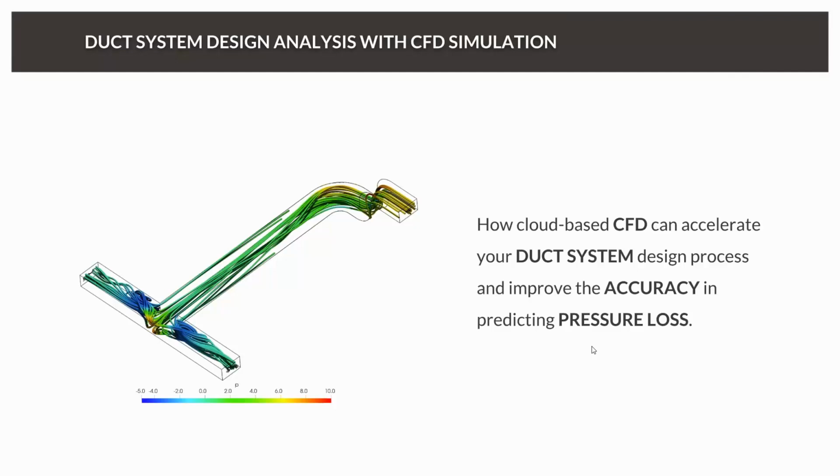And in the past, or let's say the old way of determining these coefficients, is really to put the segment on a physical test rig and measure the pressure drop. And this is something where simulation can really help, because it actually allows us to virtually calculate the pressure loss and therefore to determine the pressure loss factors without having the need of manufacturing a physical prototype.